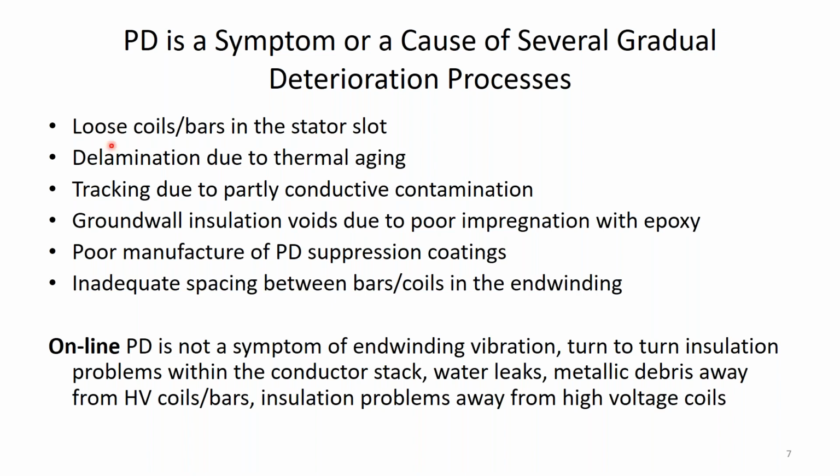Okay, there are some important failure processes we can't detect. Probably the most important is winding vibration, unless you're right at the end of life. So remember I talked about the coils outside the slot. If they're vibrating, they do not produce PD. You have to detect them some other way.